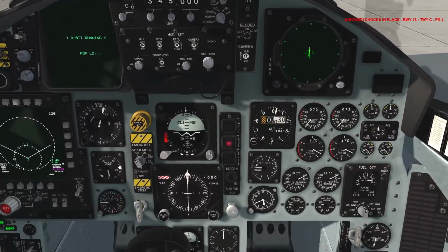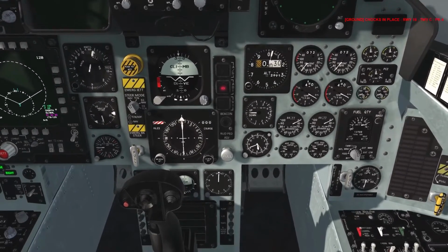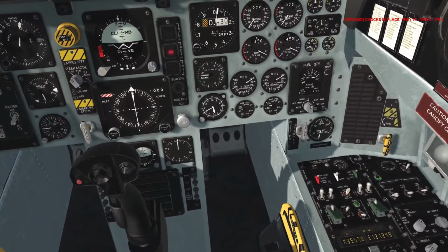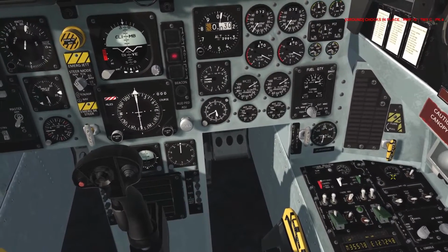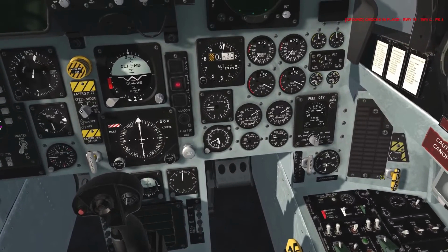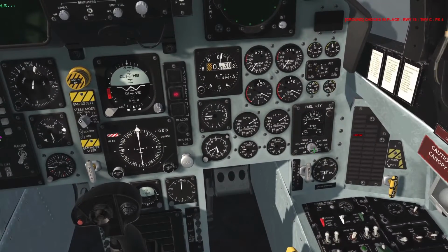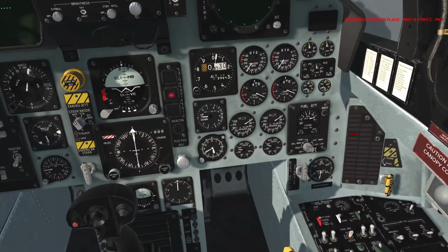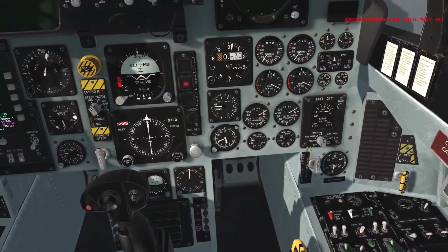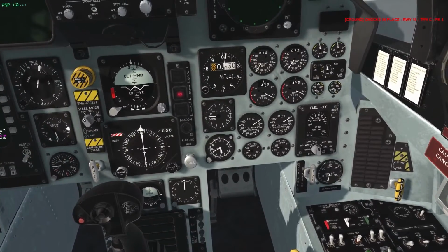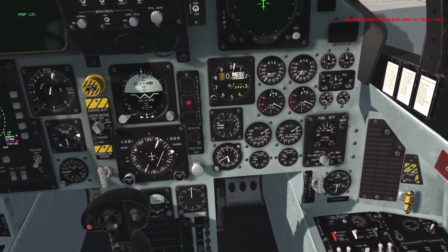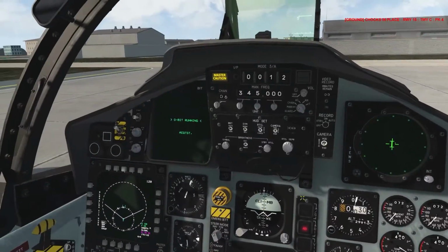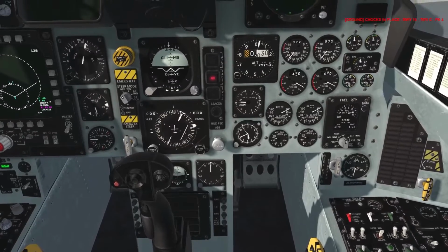But for the before taxi checklist itself, oxygen is check. We have the push button here, but that check is not functional. Fuel quantity, this is functional, so you can just check your fuel quantities and the bit. The avionics as required, so we'll skip that for now, but that's the radar, set up your ILS, TACAN, any VSD or radar modes, even though it's still in bit, so we probably delay that for a bit.